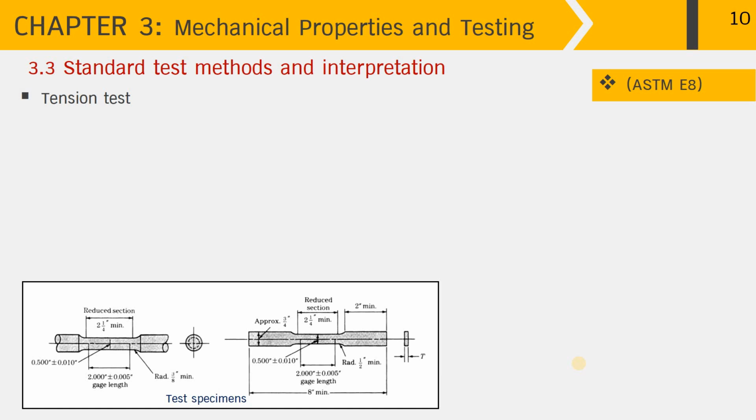And to do the mechanical test, first thing you have to remember, you have to pick up the standard test methods that suit you. And this depends on the criteria from the companies that are producing the metal products or the customers who need the standard records of the metal product forms. Right, what do we need for standard test method? We have to have standardized test specimens and the standard test machine. These 2 categories are very important.